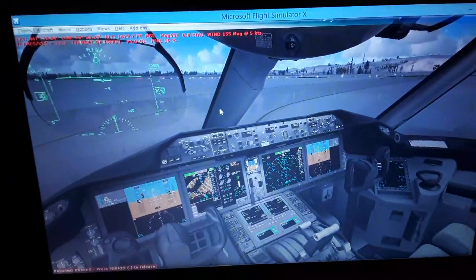The LSZH localizer has a unique radio frequency for its runway, airport and heading, so we can use 136 degrees for this runway, runway 14 at Zurich International Airport. So you will see how we're going to use the LSZH localizer for the horizontal alignment and the vertical glide slope for approach and landing, and also we can see it in takeoff.